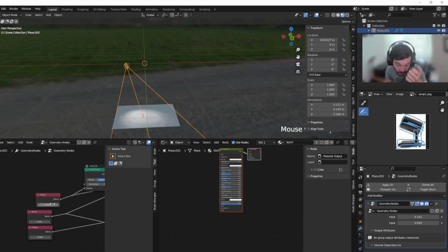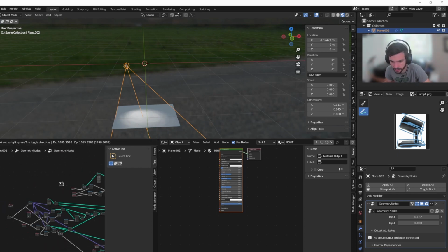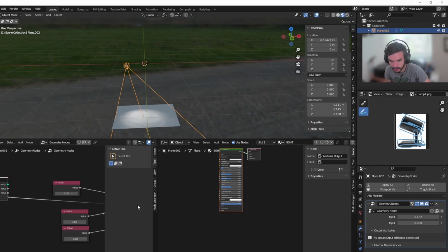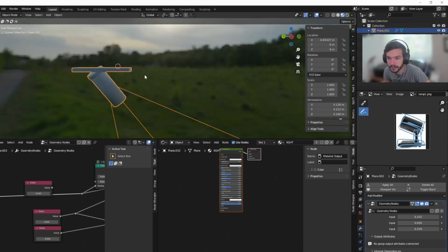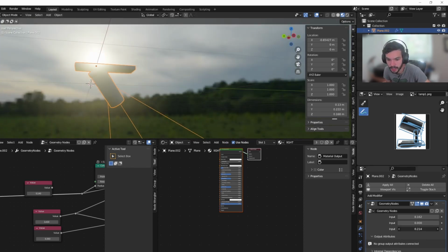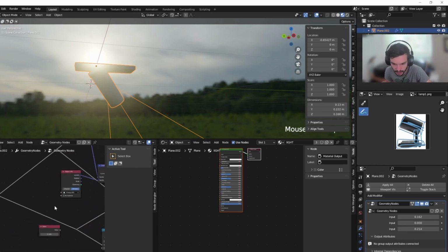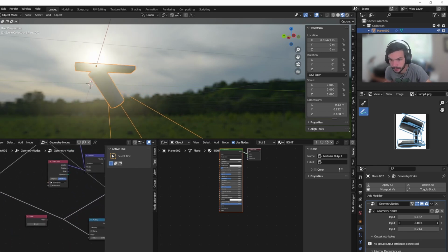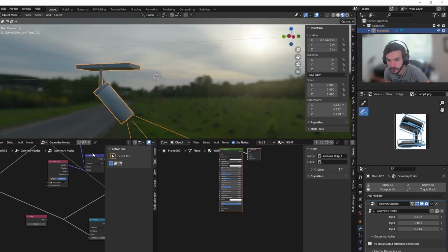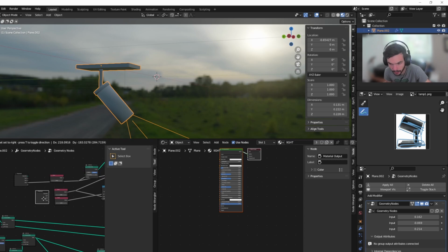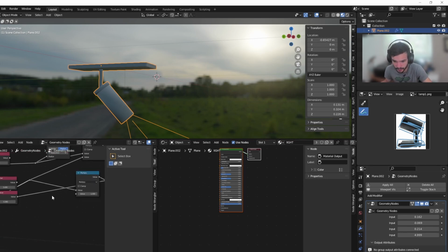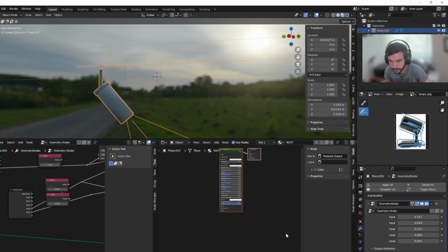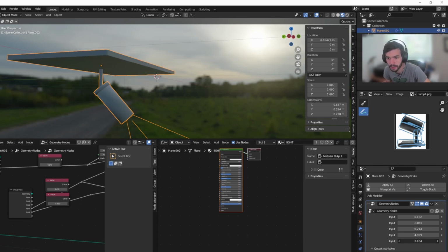Like any of these values that we created, we can just grab our group input node and plug in values here and control them outside. So if we want to make our base a little longer, make it longer. If we want to change our height, change it. You want to change another thing, like this value over here, you can just move it, and our length, this other value, shift there, and this is our thickness.